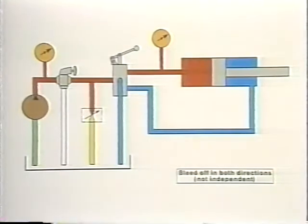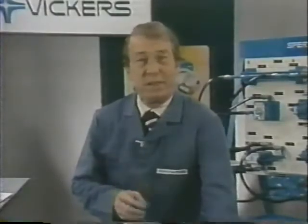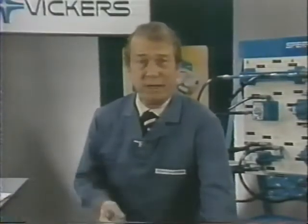This is known as a bleed-off circuit. In this case, unlike the meter-in or meter-out, there is no excess flow going over the relief valve, and our pump operates at only the pressure that's needed to move the workload on the cylinder, and this saves energy. The bleed-off circuit will not prevent it from running away.